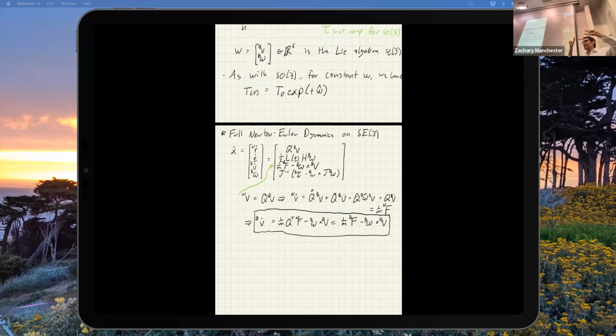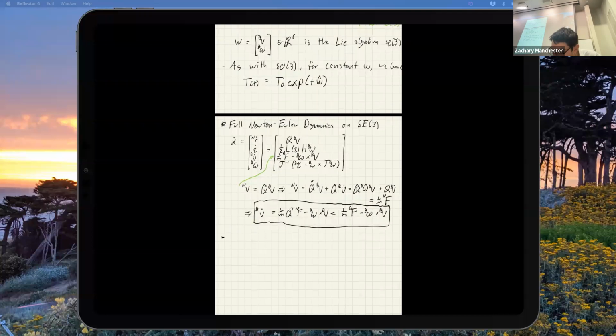Okay, so this is SE3 dynamics. The SE3 part is really the top two lines, right? The kinematic stuff. The dynamics part is basically writing down F equals ma in the body frame, which gets you this extra term, and then Euler's equation, which we already had in the body frame, to be consistent with the velocities being in the body frame. Just for completeness, because you'll see it a lot because it's super common. If you don't do it the SE3 way, it's sort of easier.